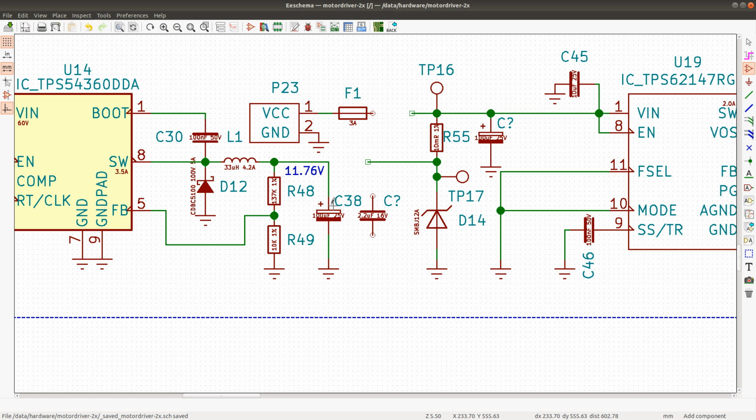I have to design something that has the best chance of working, but if I'm going to fine-tune it, I have to do it later after the board is manufactured. So I'm going to add this capacitor just for the sake of lowering the ESR on the output. We'll have an ESR that is lower than the lowest ESR of these two capacitors, and a capacitance slightly higher than 100 microfarads.